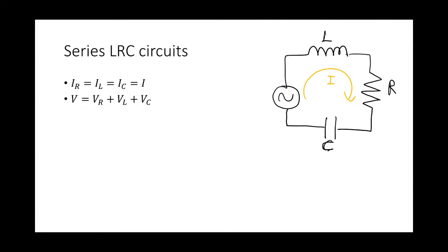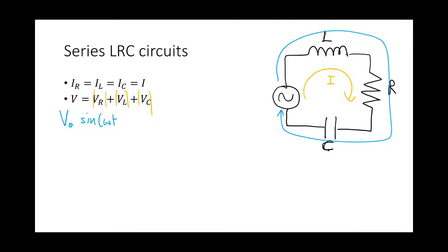You also know that you have the loop rule. Technically, these are all magnitudes because they're all against the voltage source. So whatever voltage the voltage source is applying, by the time you go through all the different components and get back to the source, you should have 0 voltage. So whatever you're supplying gets used up in all of those. So then that's going to let us write, that's my input, it's equal to